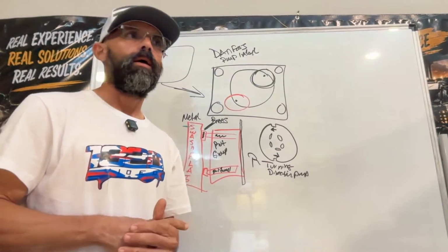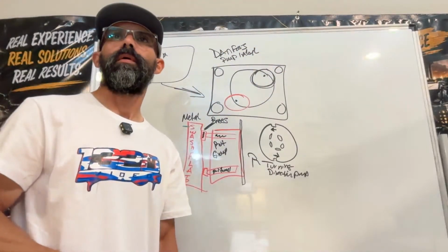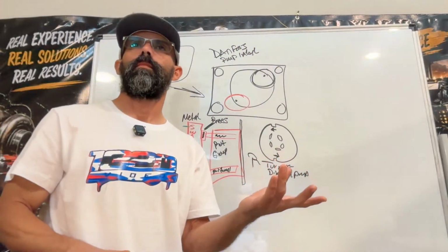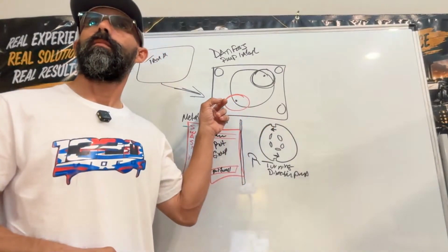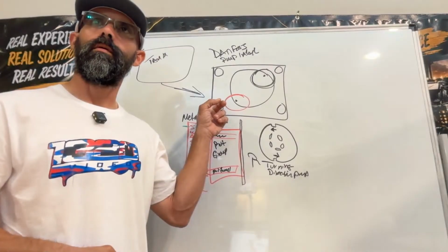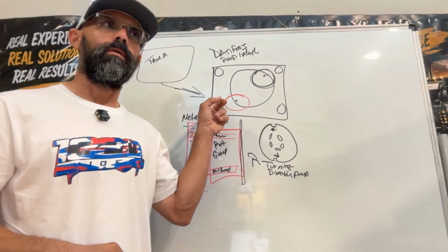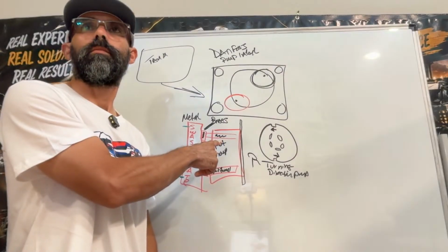You know, but saying no, yeah, it's the pump, boom, bam, put it back on the machine. Hey, wait a minute. What happened with the metal shavings that got trapped in some of the valves or some of the lines, or anywhere else? They're going to end up destroying the pump or something else.